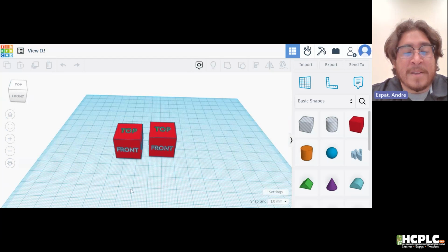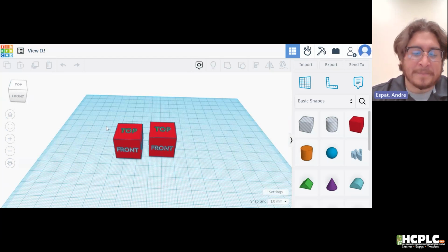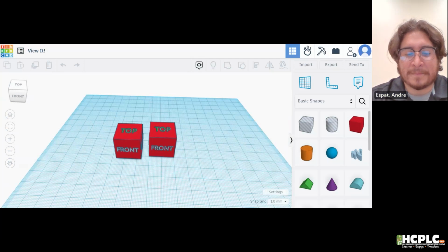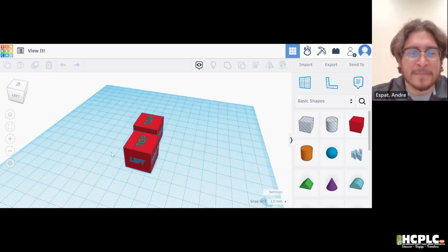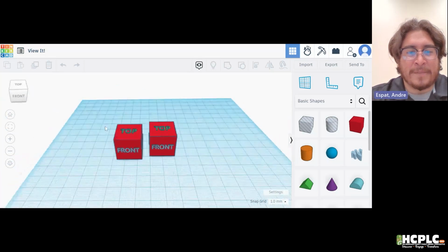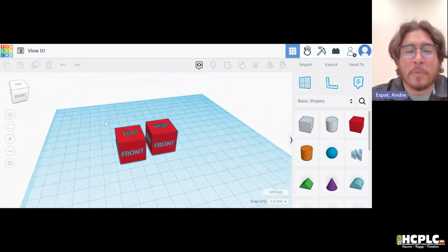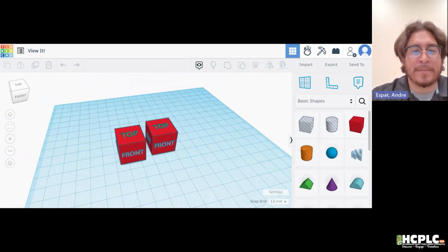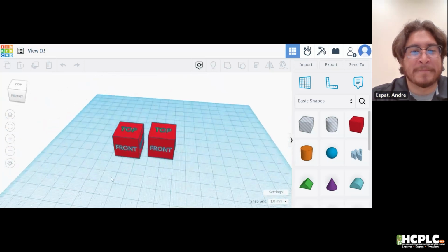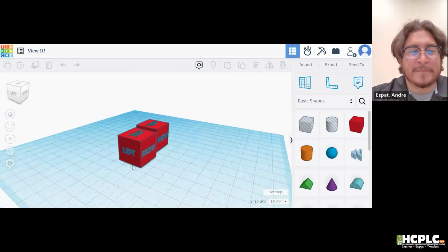Going over those, if you have a mouse handy, the same controls for camera would be your right click. So if I wanted to, I can right click on the mouse and then I could manipulate the camera just like I did before. If your right click doesn't work quite as well, you can do the same thing by holding control on the keyboard and then left click, and it'll also do the same thing. Pretty cool, right?